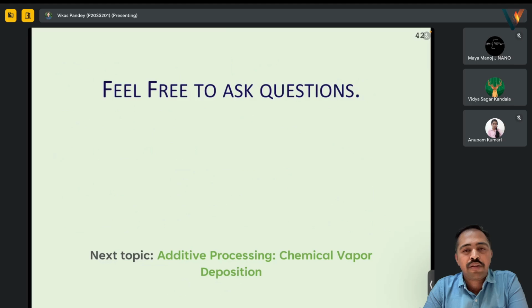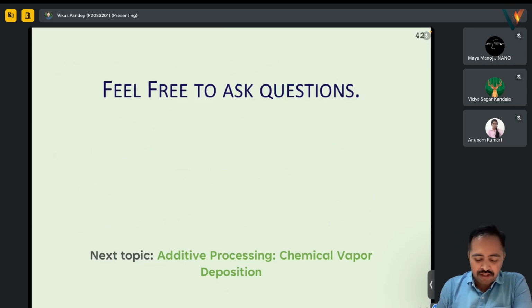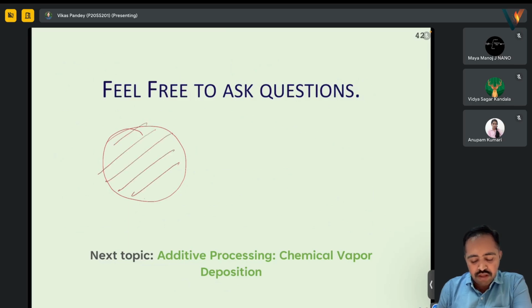Generally, you start with a blank wafer, nothing is made over it, and then you grow oxide over it, so complete oxide. And then whatever pattern you want, like you want the oxide removed from this area, and this area again we want to get to the silicon. So we will create a mask that will cover all other areas, just leaving these areas open.